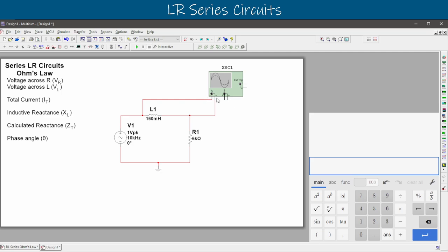The resistor one needs to be on channel B here, so the positive can go to the front side of this resistor, right here, and the negative terminal can go to the back side of the resistor. If you get those backwards, they'll read backwards.